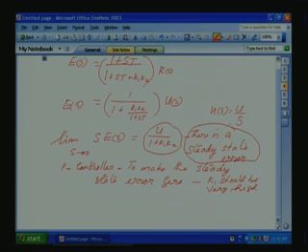So, we will not be using it in this case, but okay, this is one case, and in some cases a proportional controller is sufficient to make the error 0 for a system. So, now we are going to study PI control of a first order plant. So, here a steady state error can happen unless K1 is very high.